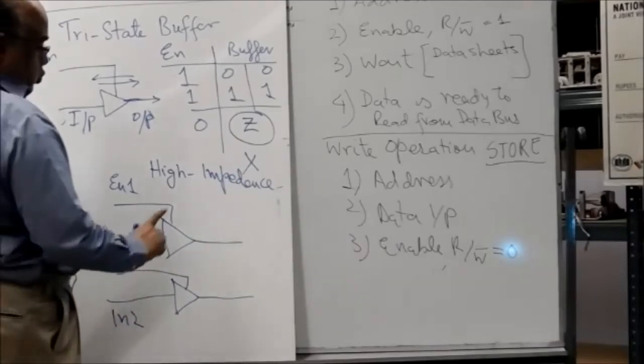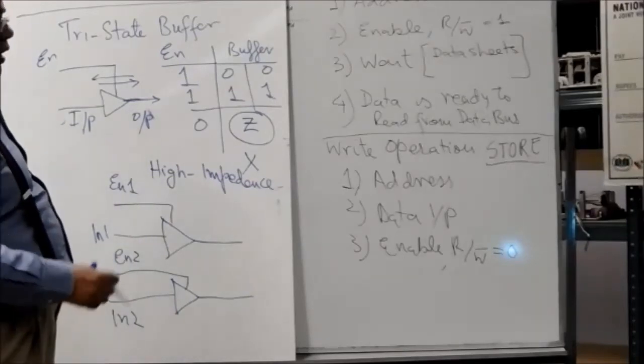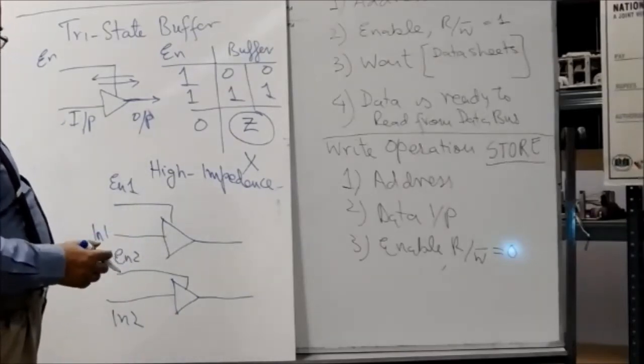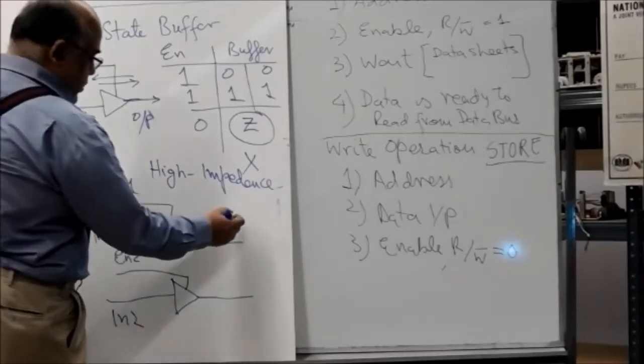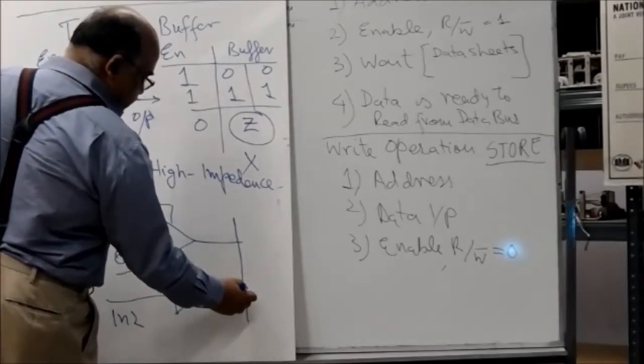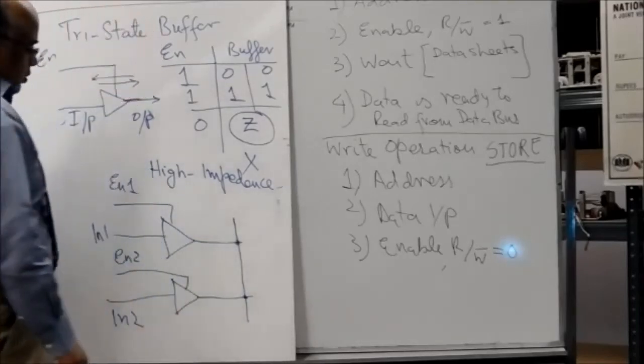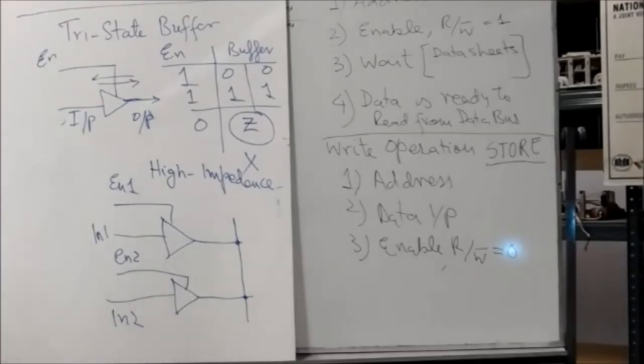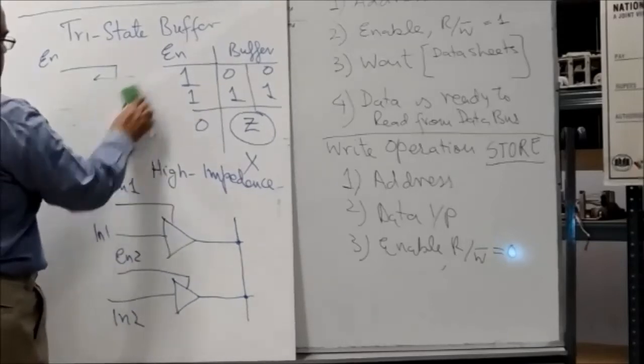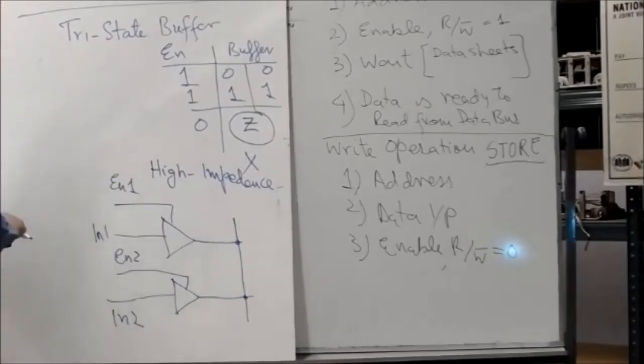Now what I can do is, usually you will notice that we have never done this, that we can short the outputs of the circuit. With a tri-state buffer, you can do that. With that, there comes a huge responsibility also. When you do that, it's not a small game now.